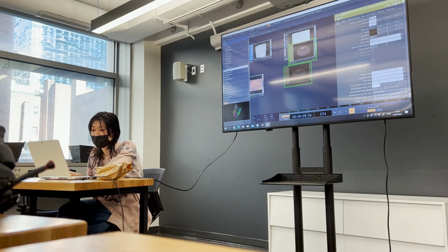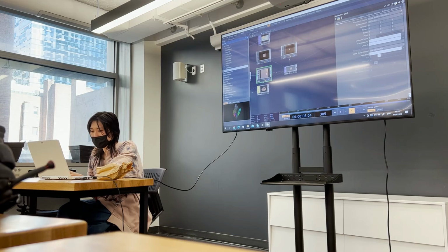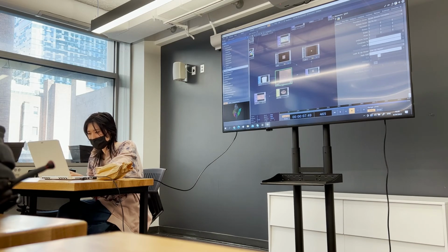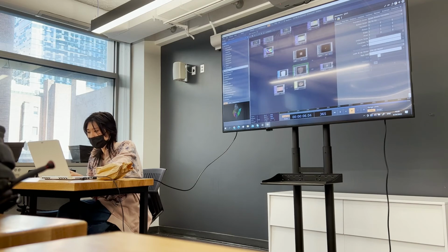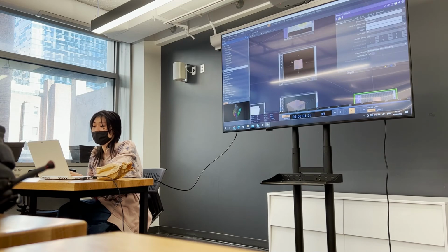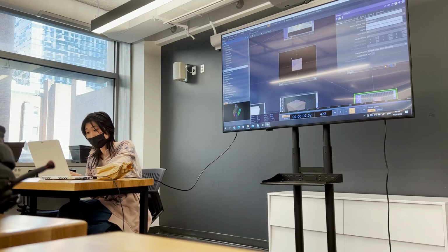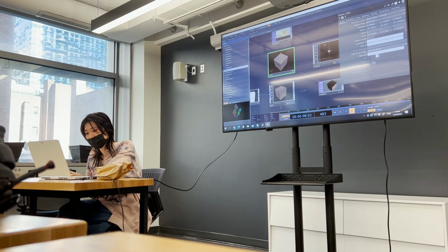And then we can drag this MAT onto the geo and select material. Then this box, actually, let's see, in 3D space, actually has this texture on it. But you can see if it changed here, it doesn't change the render because it doesn't change the camera position. But there's a very neat feature in TouchDesigner: if you click Viewer Active for the camera, you drag it around, get the angle you like, it is actually going to change the render. So this actually changed the camera's transform by just dragging around in the viewport.